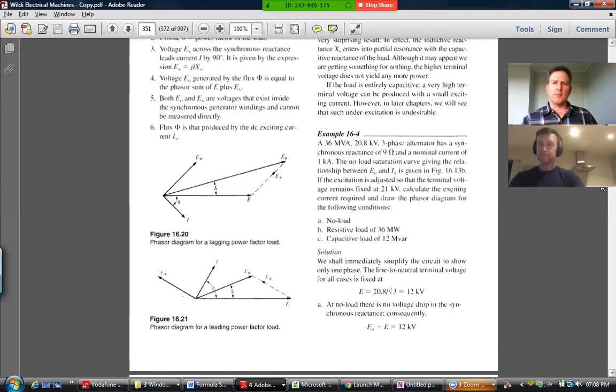And if the system gives power or reactive power, whatever it is, it's probably going to give it in terms of the system as a whole. So divide that by 3 simply if you want to get the power per phase or the reactive power per phase. And then really that E there was the terminal voltage, that's what the load was going to see if you were supplying a particular load.